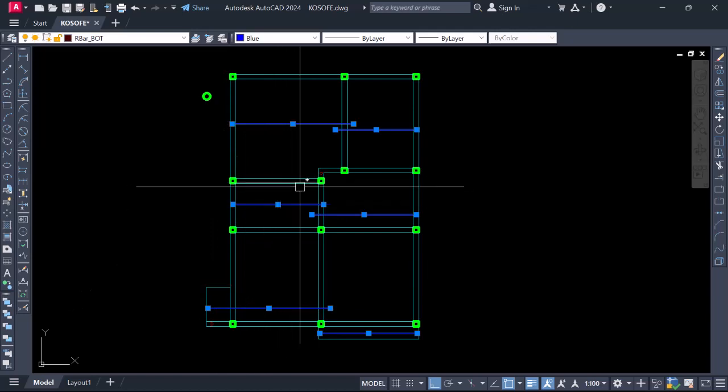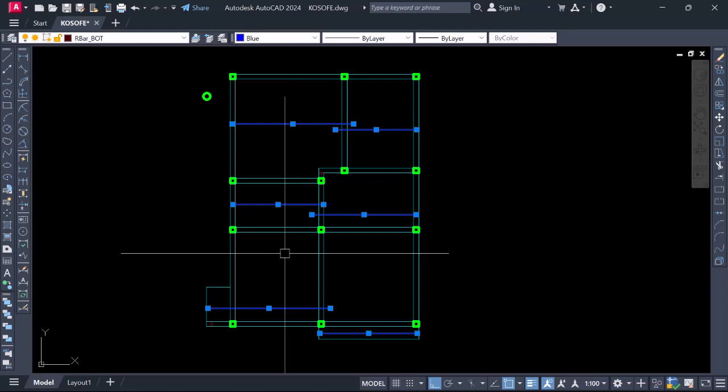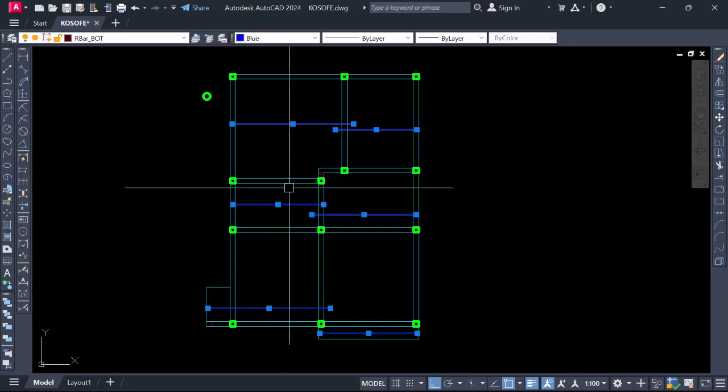And this other reinforcement will be running across this panel because we have the same dimension, right, from this point down to where we have this beam. All right, so when you're designing on site, you always run your reinforcement down to where you can have the beam, and you cross over and you continue your details. So that's why we're going to place them panel by panel.